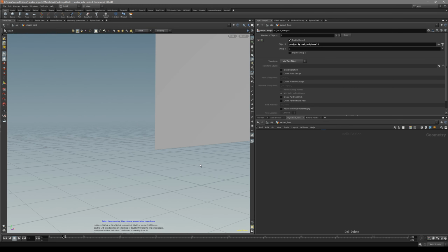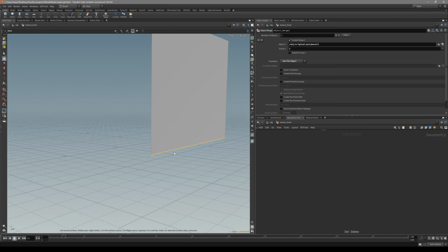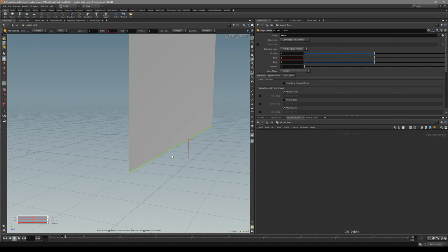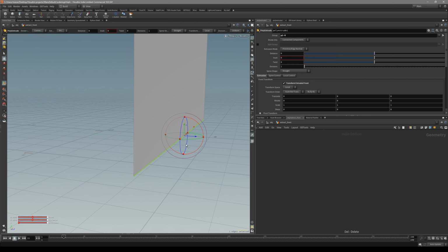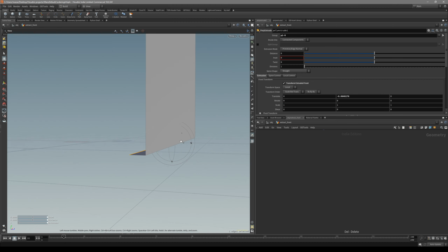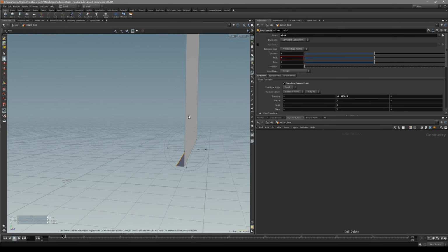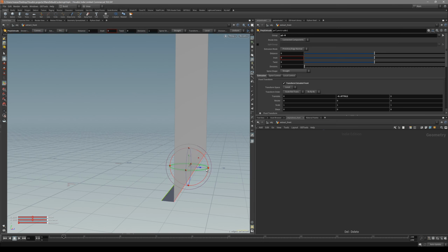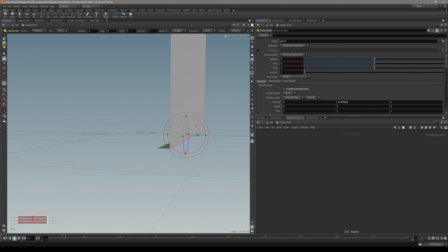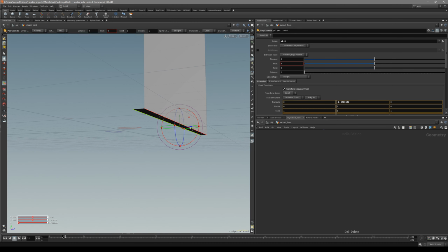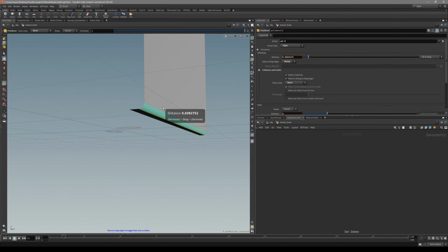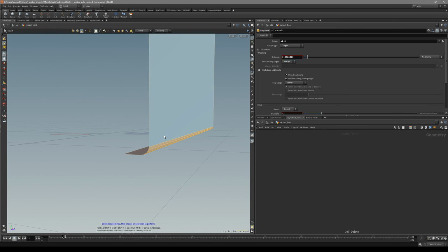Now let's go to our front piece, select the bottom of the piece, press the extrude tool and press F. F is going to give us the handle, and then we can just move it inwards like that. You can see it's kind of like extrude, only with polygons that do not have any thickness to it. It's just a plane. But with F, we can toggle between transform, extend, front. After that, something like this. Let's bevel it, like that. And now let's start extruding it.